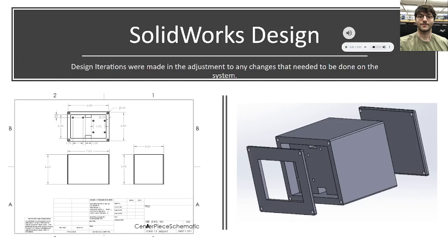The design was done through SolidWorks under the need of having the device portable and organized. The design is a simple box design that has two cavities meant to hold the electronics. The design would be holding the LCD screen in the front, while the microcontroller, converter, and battery pack will be in the middle cavity and will be sealed by a back cover. The material that makes up the device frame will be PLA with screws connecting to each corner of the frame.